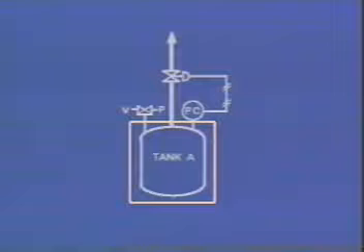When used in a dissipating application, control valves provide a pressure letdown capability or pressure dissipation. This drawing illustrates an application in which pressure is dissipated. The fluid in tank A is processed at high pressure. During processing, pressure tends to rise. Excess pressure is relieved to another step in the process. The control valve in this process provides the pressure letdown service. Energy, in the form of pressure, is dissipated by the control valve.